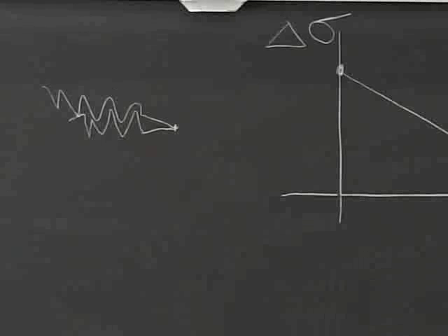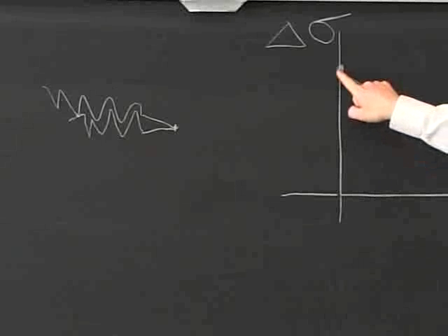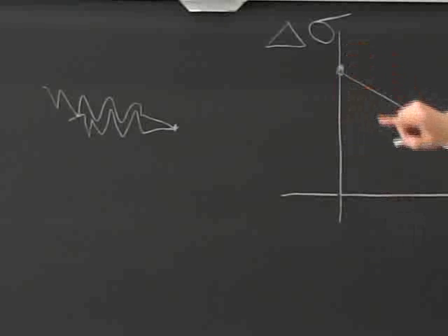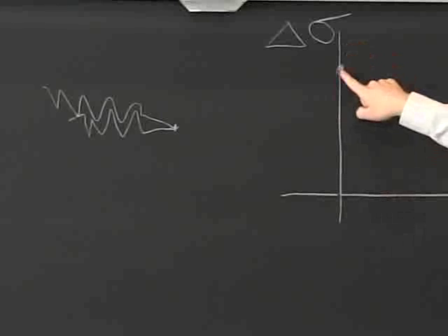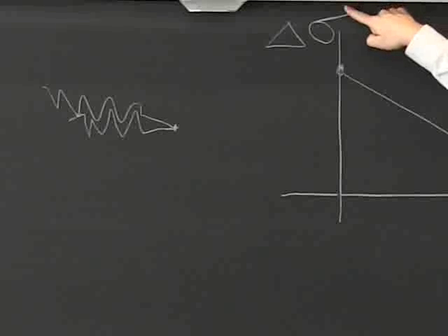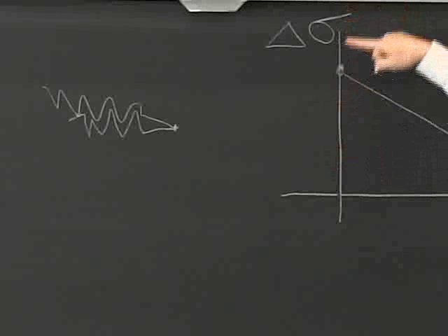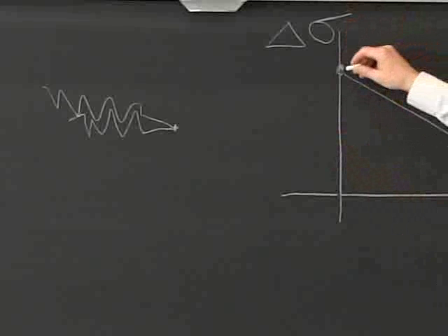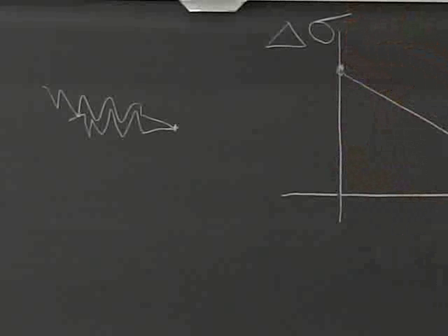But from there, you can say this is 10 to the 7 cycles. If, like I'm doing on my plot, I say it's only 10 to the 5 cycles that I'm looking at for fracture stress, then it's going to go up or it's going to go down. So you just vary this point here as you need to. And then you can make it into a curve if you use a second order equation as opposed to a straight line.